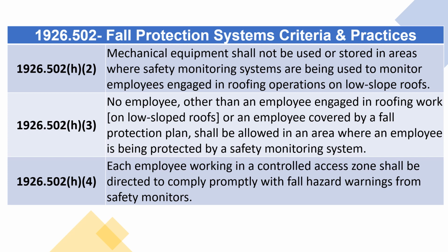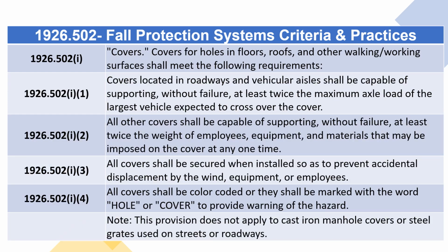1926.502 H4. Each employee working in a controlled access zone shall be directed to comply promptly with fall hazard warnings from safety monitors. 1926.502 I. Covers. Covers for holes in floors, roofs, and other walking/working surfaces shall meet the following requirements. 1926.502 I1 through 1926.502 I4.